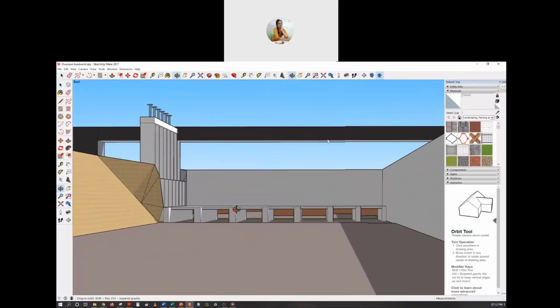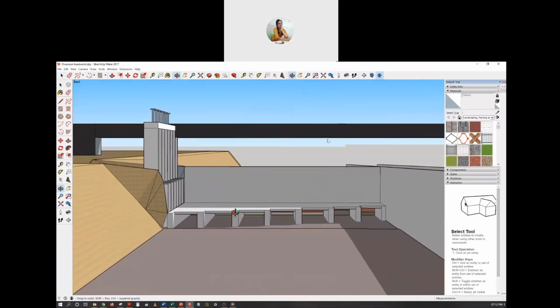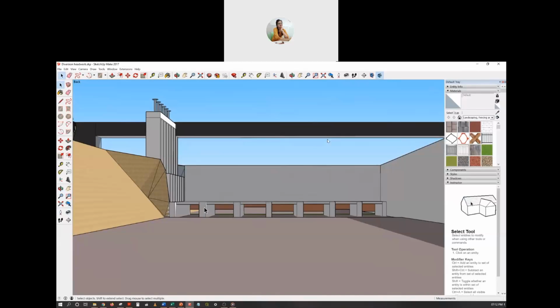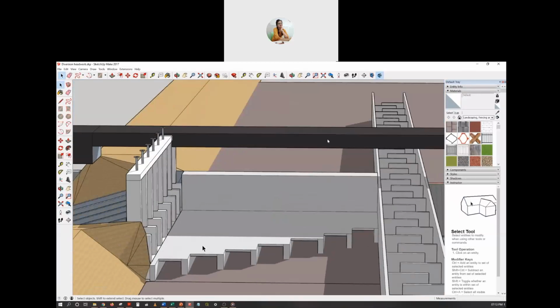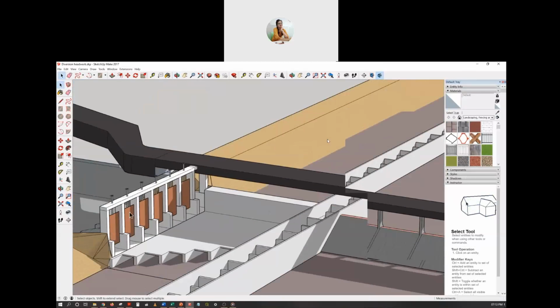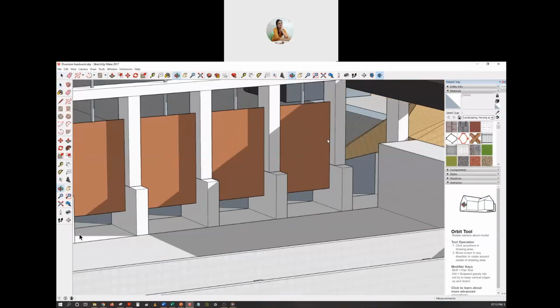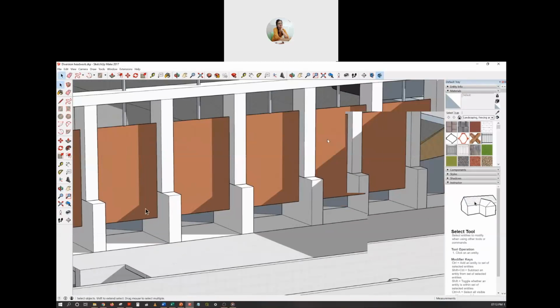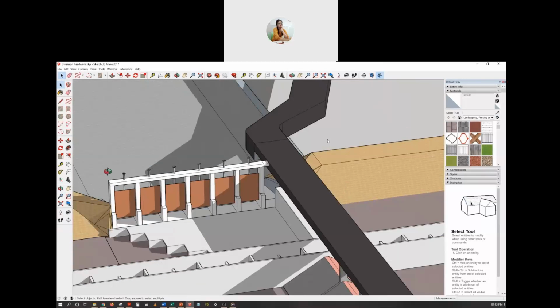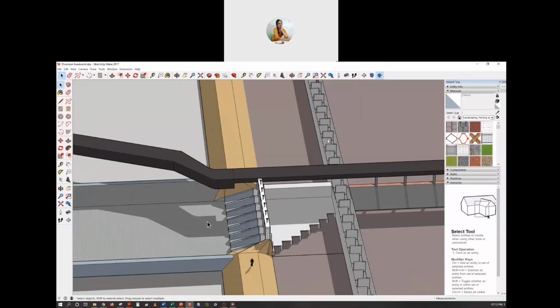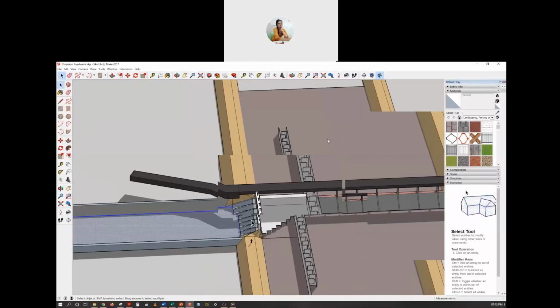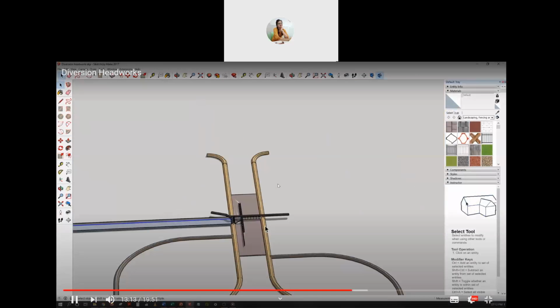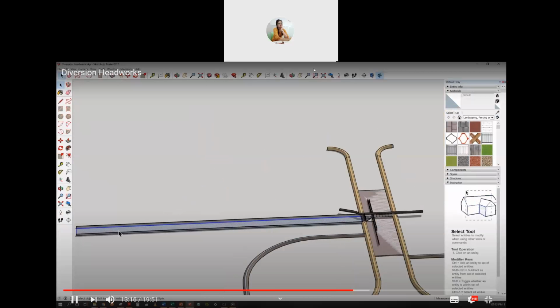These are some more gates here, here, here. Each of those gates is supposed to be opened by a different amount. Now, in this part, all the silts that are carried by the water will be stored and trapped so that water entering through these openings will be relatively clear, and therefore in this canal we get some cleaner water. So this canal will go a long way based on the command area.